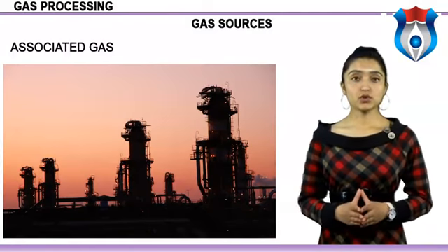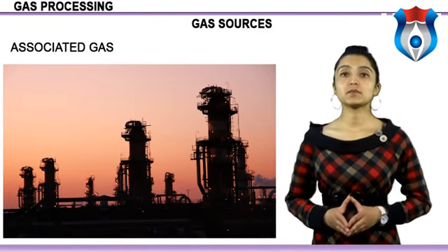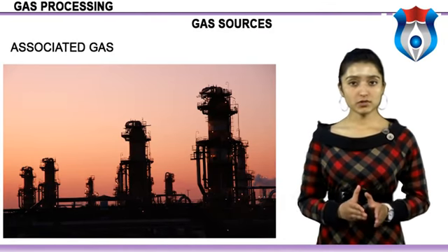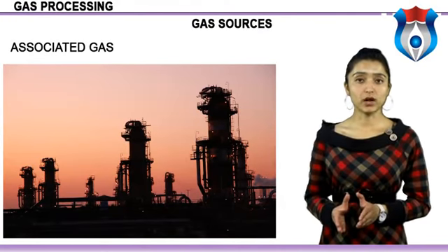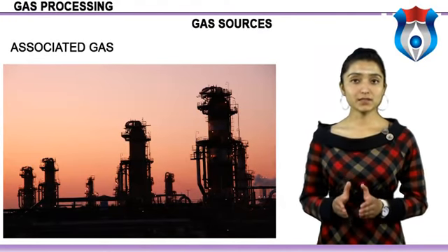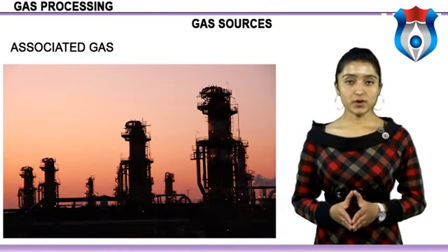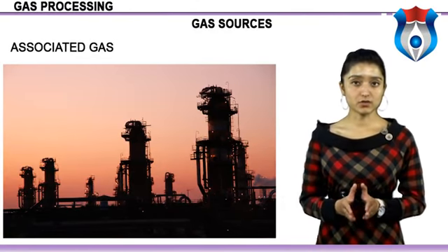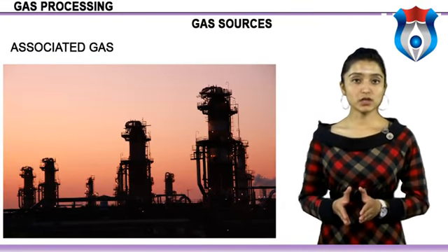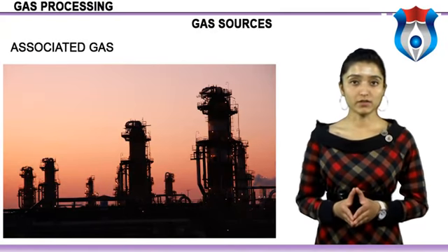Properly designed crude oil well completions and good reservoir management are used to minimize the production of associated gas so as to retain the maximum energy in the reservoir and thus increase ultimate crude oil recovery. Crude oil in the reservoir with minimal or no dissolved associated gas is rare, and as dead crude oil is often difficult to produce as there is little energy to drive it.